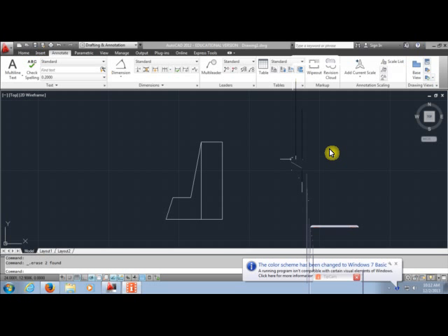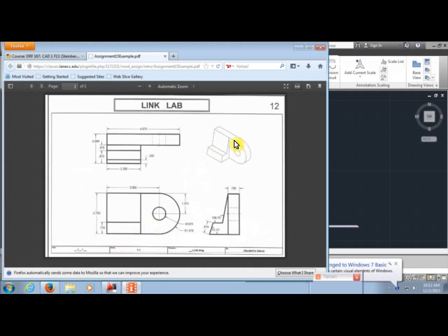Okay, then it wants me to draw the other lines, and what I'm going to do is draw the section that's going to be out to my arc, because I want to show you guys how to create this arc using the ellipse command in isometrics, because it's a little bit confusing for people sometimes. So to do that, I need to figure out what the exact length is before it turns into the circle.